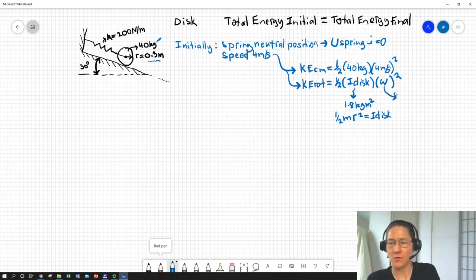Okay, and for a body that's rolling, we can relate the point of instantaneous zero velocity to the velocity of our center of mass, which we know is 4 meters per second, and the angular velocity of the rigid body using our rigid body kinematics, and with the radius, of course, we can get a value for our rotational velocity of our wheel, whose center of mass is moving at 4 meters per second.